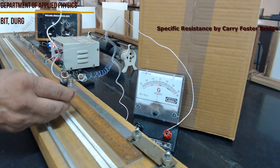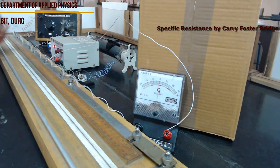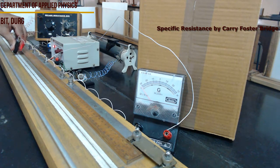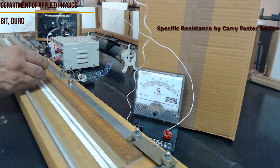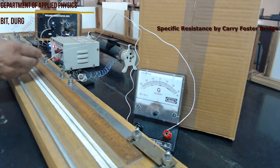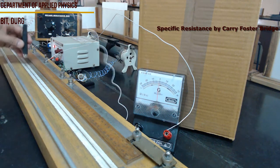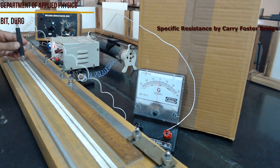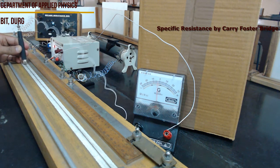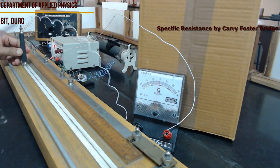You can see, if I keep the jockey towards the right side end, the deflection is to the right. If I keep it towards the left hand end, the deflection is towards the left. So in between there will be a point where I get null deflection. I am lifting up the jockey and putting it on the wire. I am not sliding it on the wire to find the position of the null point. You can see this is the position of the null point. Here I get deflection. Here also I get deflection. But see, this is the point. At this point there is no deflection. So this is the reading for 0.1 ohm.